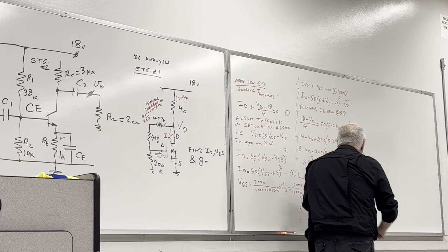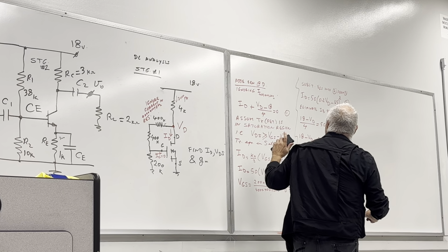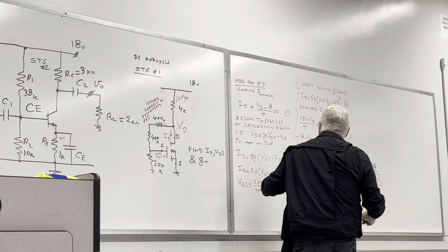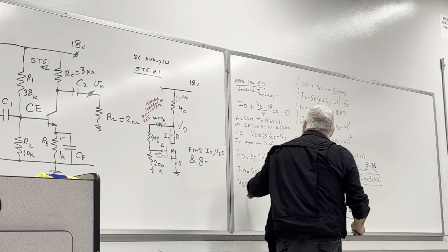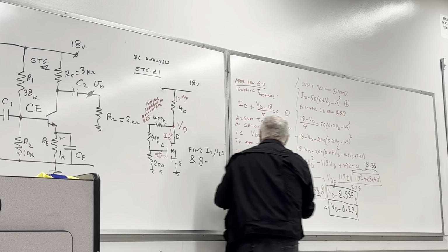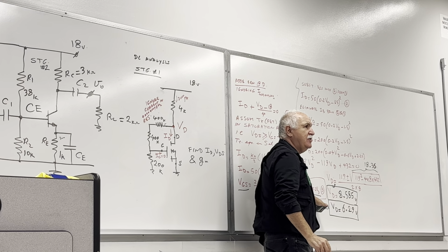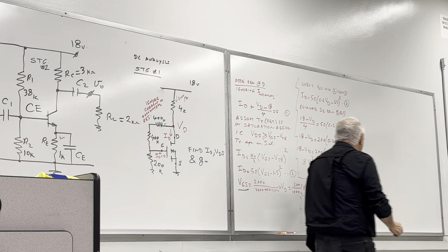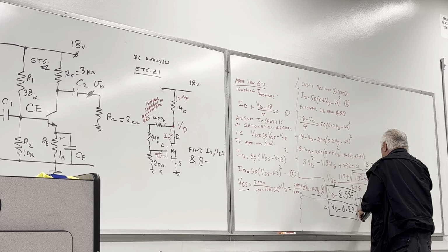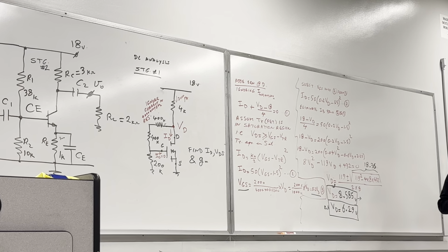Having figured this, you take the VD into calculating the VGS. That's the trick. So remember what was the link between VD and the VGS? Right? What was the link? 0.2 times, yeah, remember? So if you take this answer as the real solution, it's going to be 0.2 times that.